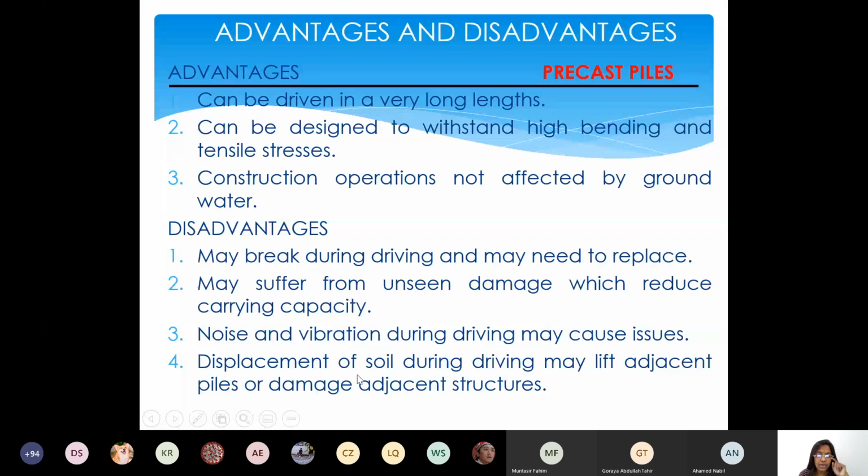Yeah. You must check the soil condition, especially when you are driving the bores, driving the casings into the ground. There will be a time taken between completion of the casing and pouring concrete, right? So in between you have to handle it properly so that there is no sliding of soil into the pile, because unwanted material going into the casing and there are chances of movement of the casing.